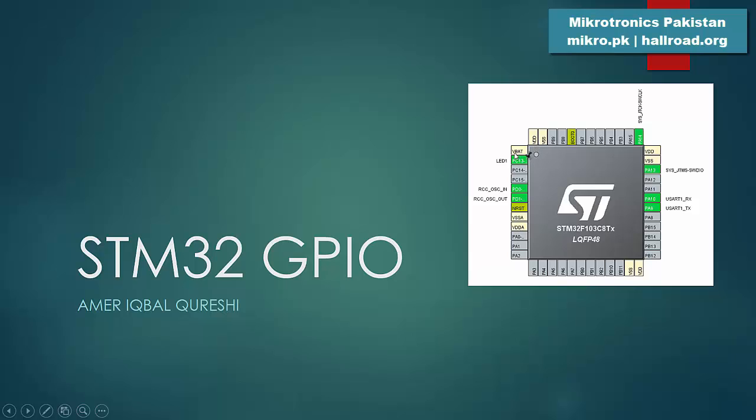And then this is the pin for the external battery to power the real-time clock, which is built inside this microcontroller. And then these are the pins PC14, PC15, PD0, PD1, PA0, PA1, PA2, PA3. These are the GPIO pins.